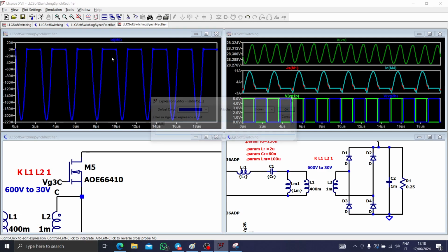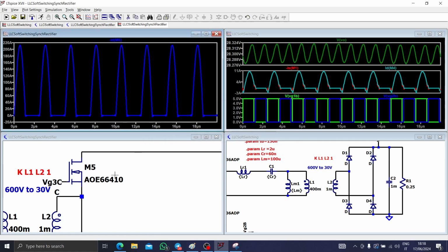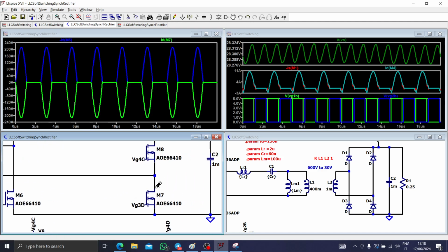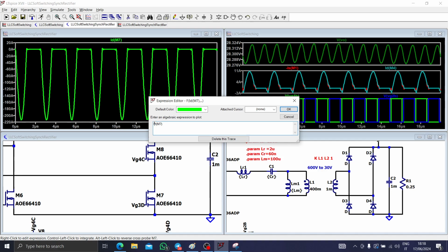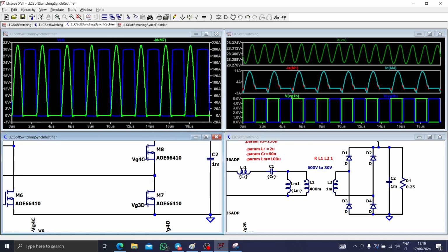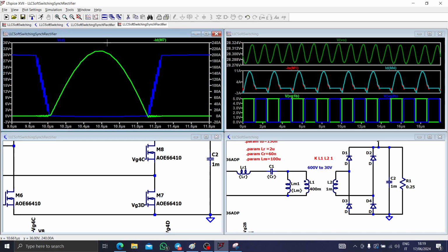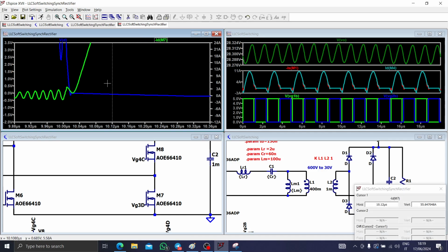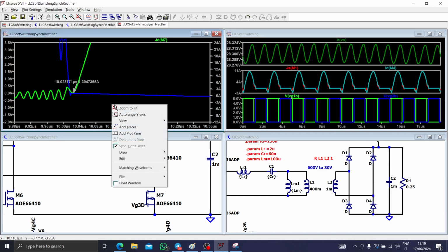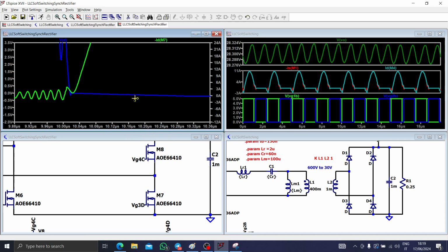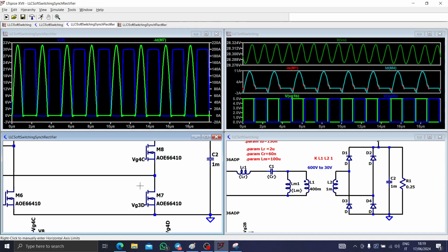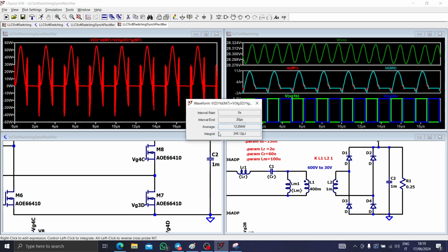And as you can see, they are the same as before. So nothing has changed, you may think. But the advantage of the MOSFET is that you can put them in parallel. So as you can see here, are we performing zero current? Well, the answer is check yourself. When does it start to switch? It starts to switch at 1 amp. Okay, so it was almost near zero current, but almost.